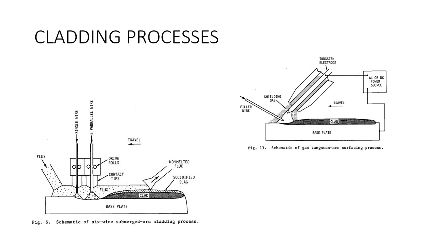And then on the other side we've got submerged arc. Submerged arc, if you've never dealt with it, is a pretty big process. This is not for little work. This would be for just puking metal on there where you really need a lot of material and a higher deposition rate. Let's say you're cladding a vessel that's 20 feet in diameter.